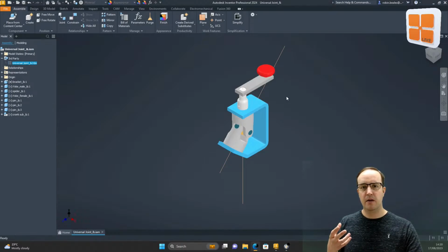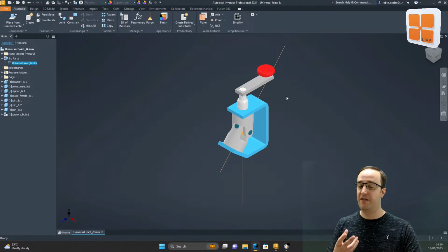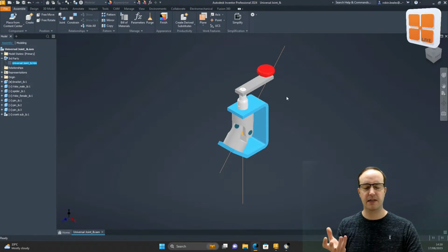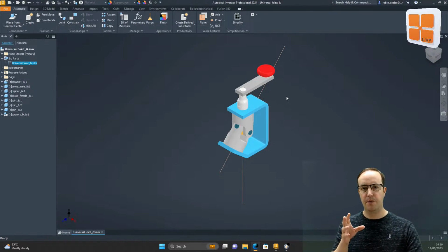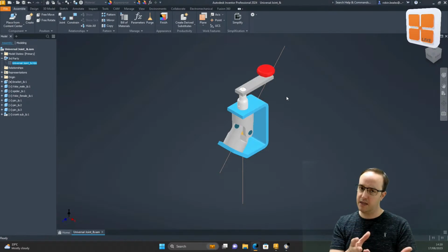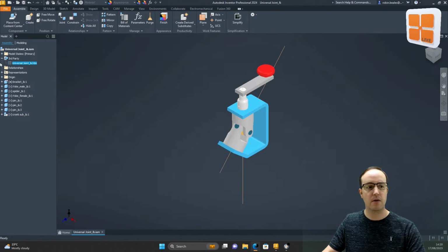You will be unbelievably surprised at how non-Autodesk CAD systems will allow self-intersection. And when you bring a model with self-intersection into Inventor, it will turn it into a composite because it will say, well, you can't be a solid because you're self-intersecting, and it will make you repair the geometry. So in cases like that, you'll get a surface model rather than a solid, and it will show you that inside of that import log.